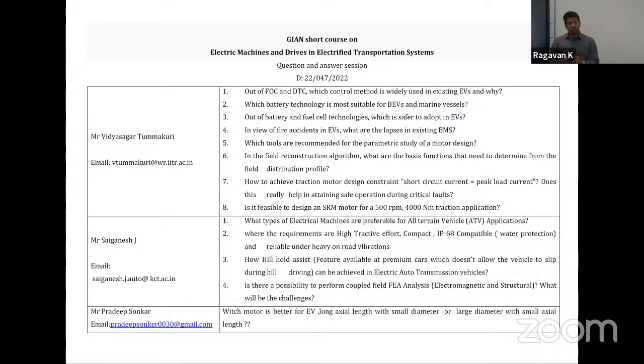If you don't have a differential, then it's a hub motor. But if you have a differential, you can connect it to the wheel, or it's sitting inside the wheel. Inside the wheel, the radius is very limited. So there's no one single answer for this, but generally speaking, if you can, we're always trying to go for a larger stack length. More torque is more stack length, so if you get more stack length, that's good.